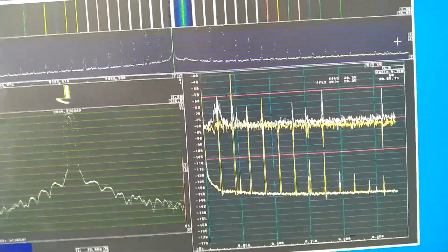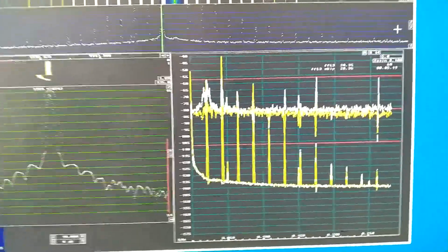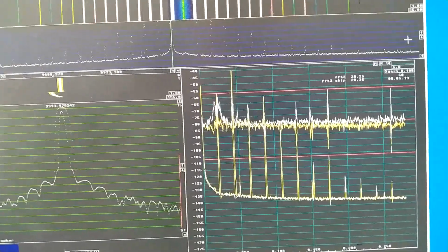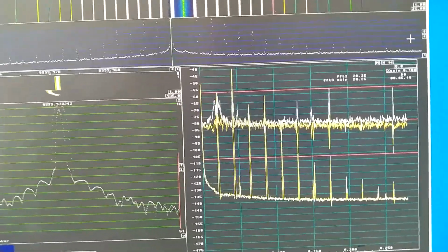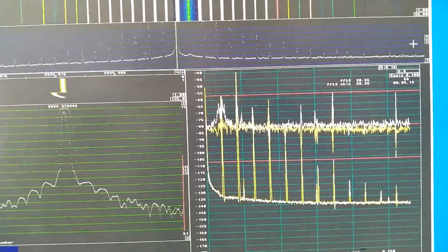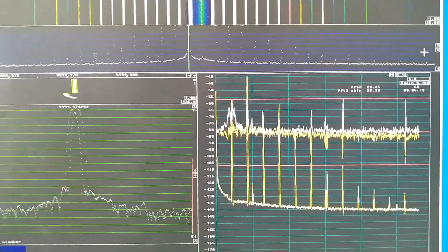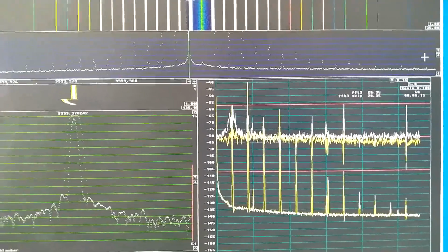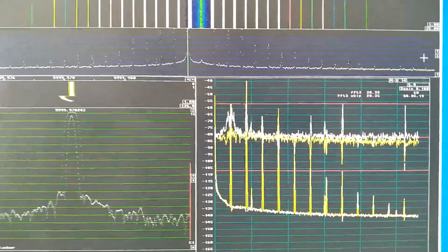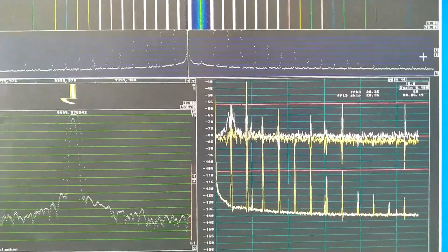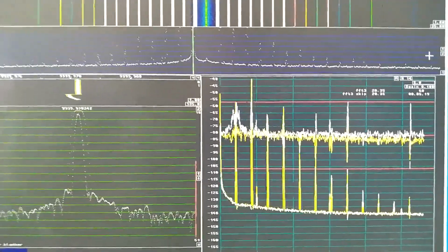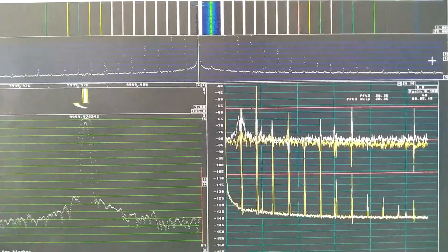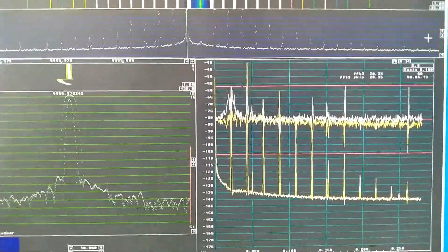But this is the only oscillator I have seen having this property, so the possibility to do something about it by detecting the amplitude modulation and doing corrections by adding the appropriate modulation in antiphase, that is not the appropriate strategy. Just choose some other oscillator if you need low noise at large separations.